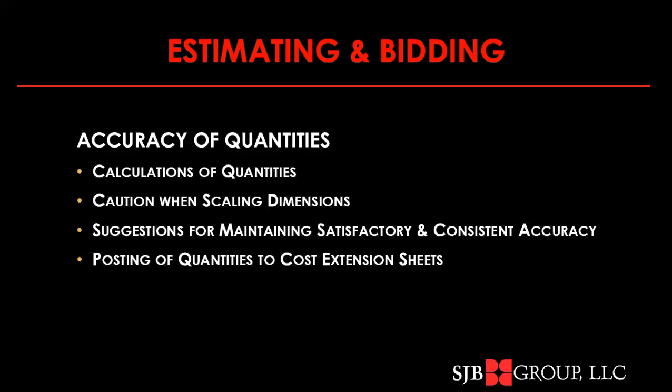When you're scaling dimensions, you never want to scale if dimensions are readily available. Before you use the scale on a detail, you need to make sure that that picture is drawn to scale and it's not just a schematic. Beware of that abbreviation NTS, not to scale.